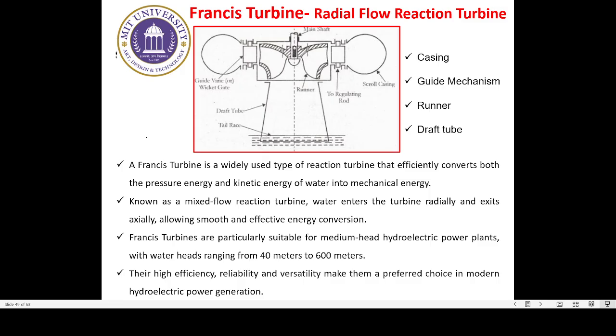It is also possible, by a suitable arrangement, that the spacing or width between two adjacent vanes of the guide mechanism can be changed according to the requirement. This feature allows a variable amount of water to strike the runner, isn't it? It means that the discharge striking the runner can be changed according to the requirement by adjustment of these vanes of the guide mechanism.